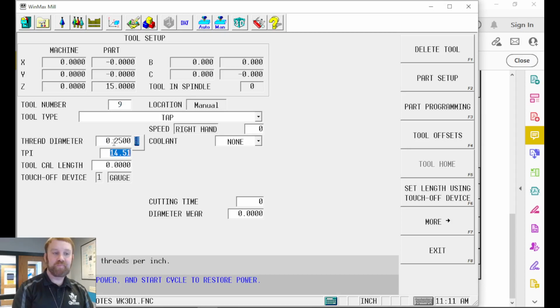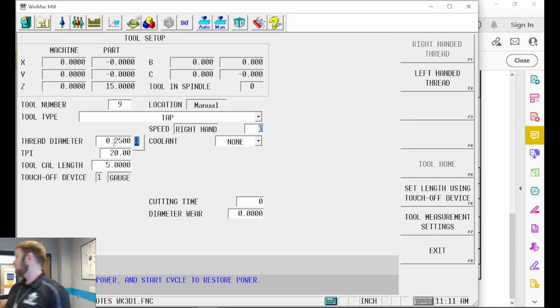So there's times where we get tooling, not necessarily the cutting tools, but for instance, on the lathe, our live tooling comes, and the gauge length of those is a metric number, like 100 millimeters. At the control, when I'm plugging in the projection length of that live tooling drive, I can just hit the button down at the bottom of the screen, convert to millimeters, plug in 100, and convert it back, and it'll automatically do the math for me. So, quick and easy, dirty conversion options.